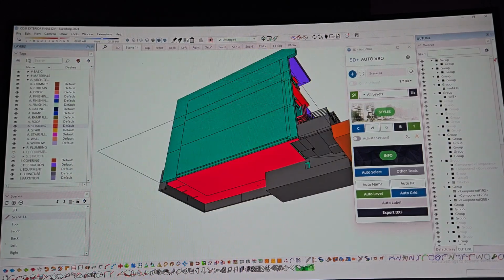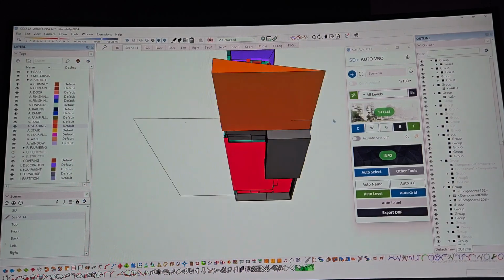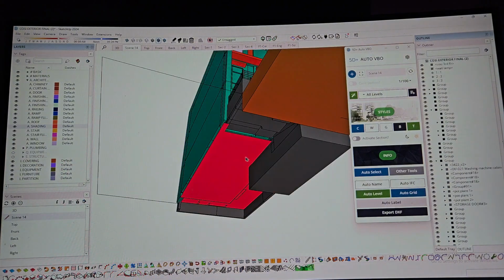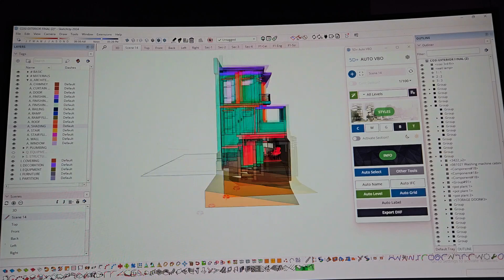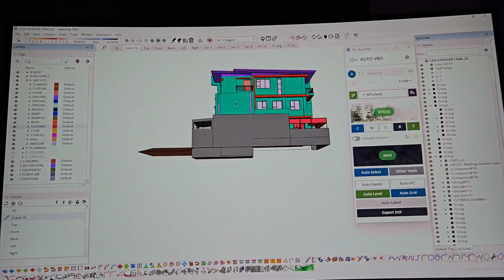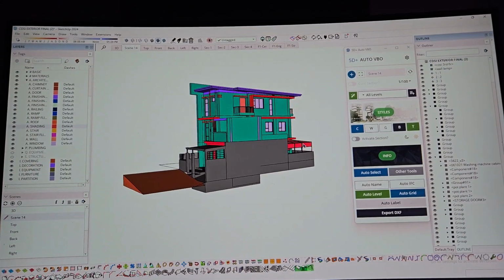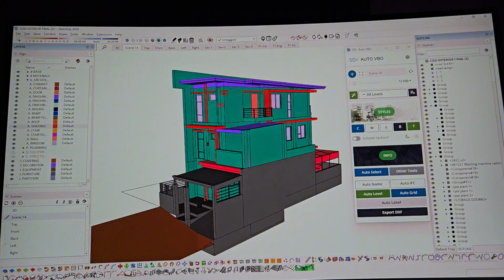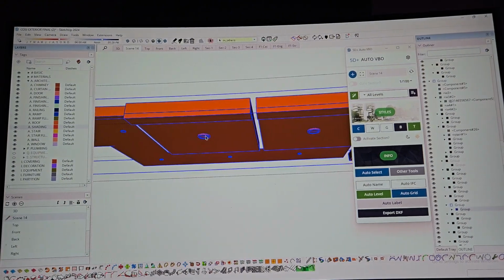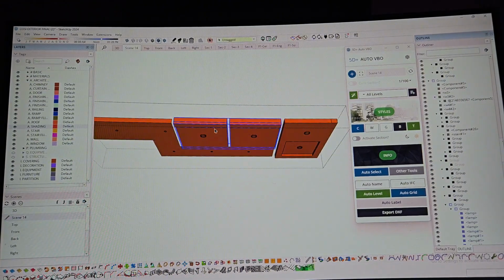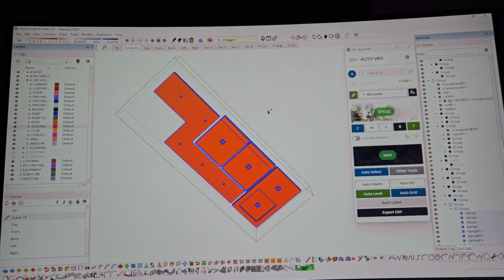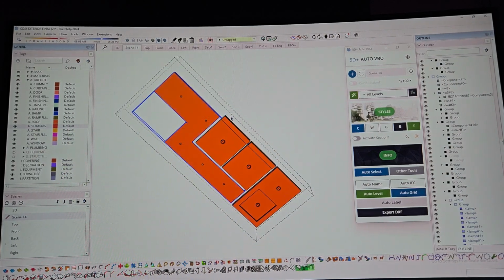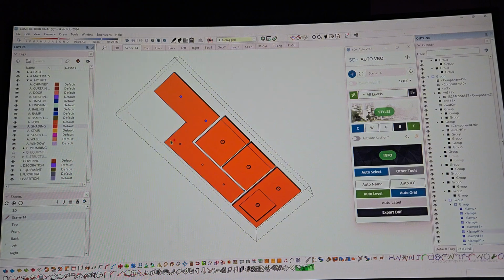So now that everything has been tagged, hopefully, right click, building elements, architectural finishing floor. I did not add structural yet. Well, it should already have been modeled, but let's see. Our lights will be in electrical, okay. So this time it's mixed with the ceiling, just like in our workflow.